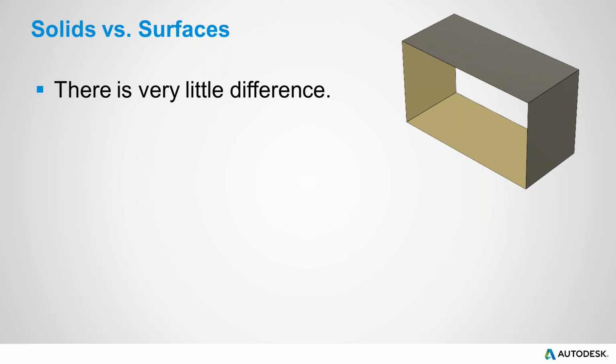So I just have the 4 faces around it. And through the API, that same structure still applies. I have one body here, and it's made up of 4 surfaces, and I can interrogate those surfaces, and I'll just get slightly different information when I ask some of the faces.